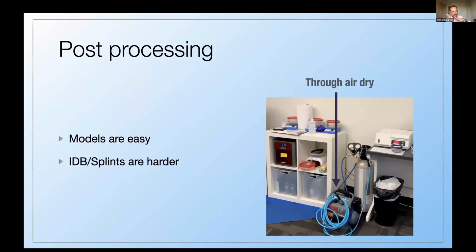But if you see a sludgy layer flowing on the surface, that's resin. You've got to go back in with the toothbrush and clean that out. It's probably time for you to change and cycle out your alcohol, at least put in a new clean wash at the end of that process. Because if you don't do that and then you put it in the light curing unit, you're kind of in trouble. Another thing that most people don't think about or even maybe know about is that some of these materials have an oxygen inhibition.